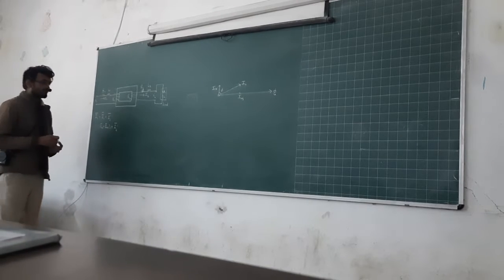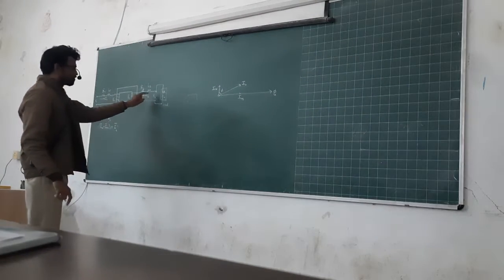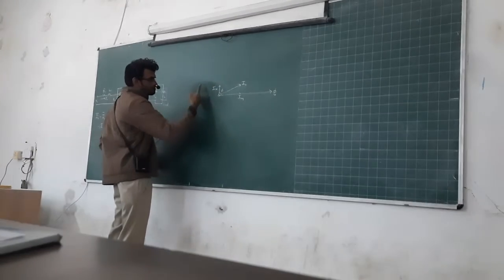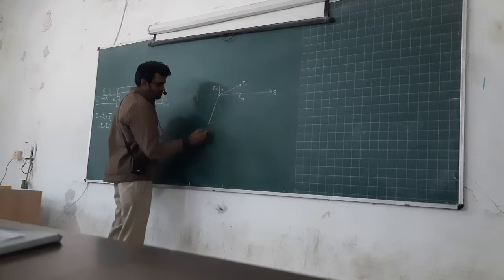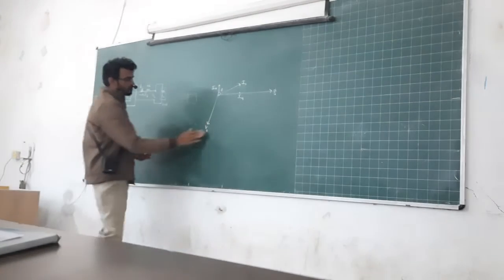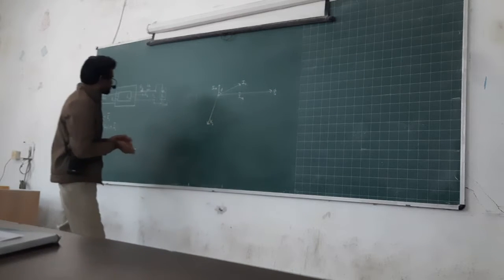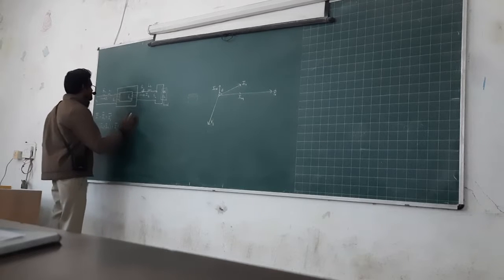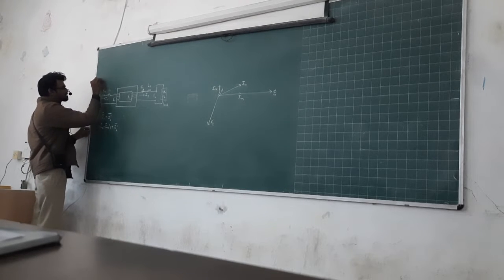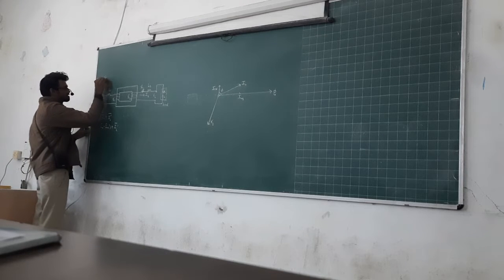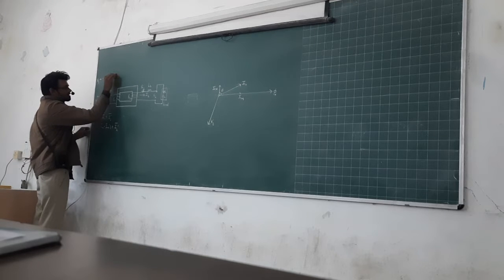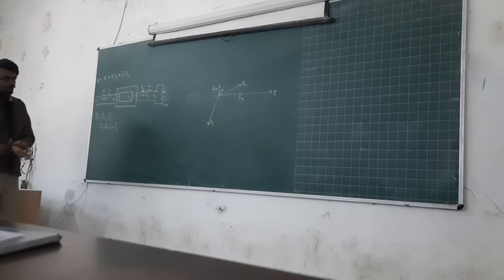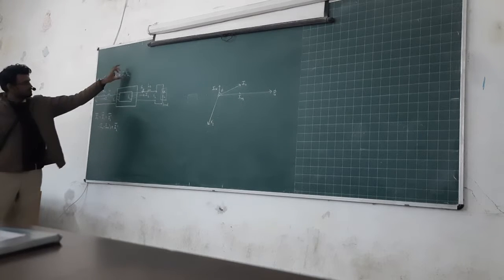Alright, we always draw the phasor of V2 in the third quadrant, at some angle. Why is that so? Because after adding the voltage drops to V2, we have to get E2, from the KVL equation on the secondary side. On the primary side, the supply voltage must equal the opposite of E1, plus the drop in resistor I1R1, plus the drop in inductor I1XL1. The supply voltage must be the same as the generated voltage plus the resistive drop and inductive drop.